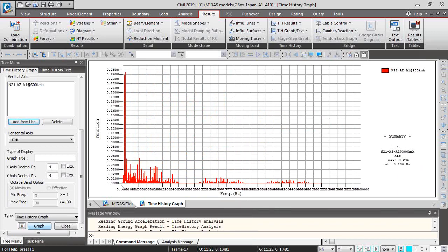If you look at that and you have everything 0 for the first frequencies, and then you have a frequency for mode number 80 that contributes to the whole vibration, then maybe something is wrong. Maybe it's fine, but it's worth checking if the results make sense.